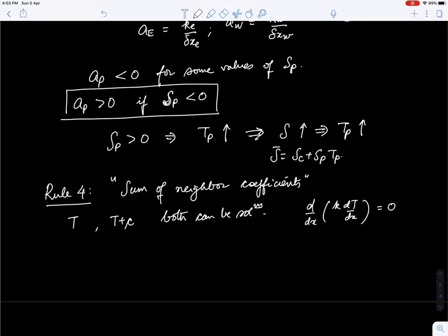In other words, if the temperature is uniform everywhere, and that's the solution of the problem, and I increase the temperature by a small amount everywhere, then the discretization equation should also reflect the fact that the temperature has increased by the same constant value, which means that the coefficient AP should actually be a summation of A NB for linear problems.